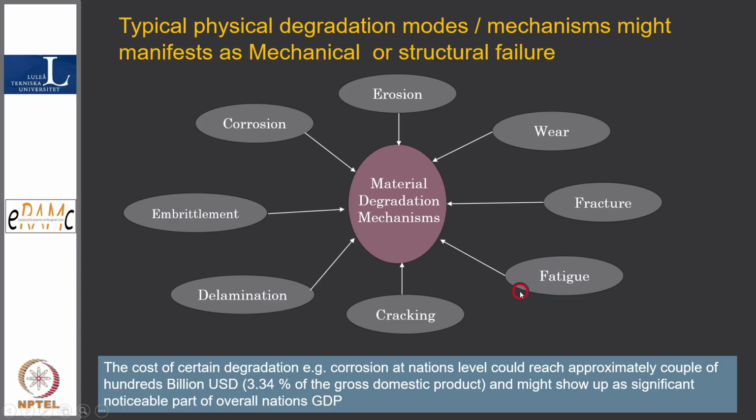Fatigue, okay. In fact, fatigue acquires a bigger dimension. Of course, it is a part of mechanical things, bridges and all, but it is equally relevant to electronics, because solder joints are a major contributor to electronics failure, and that's where fatigue failure has been seen, not because of mechanical loading but because of thermal. In mechanical components it is mechanical loading, but it acquires a high dimension when we talk about the solder joint. Sometimes it is quality, sometimes delamination; there are so many things we will see as the presentation goes on.